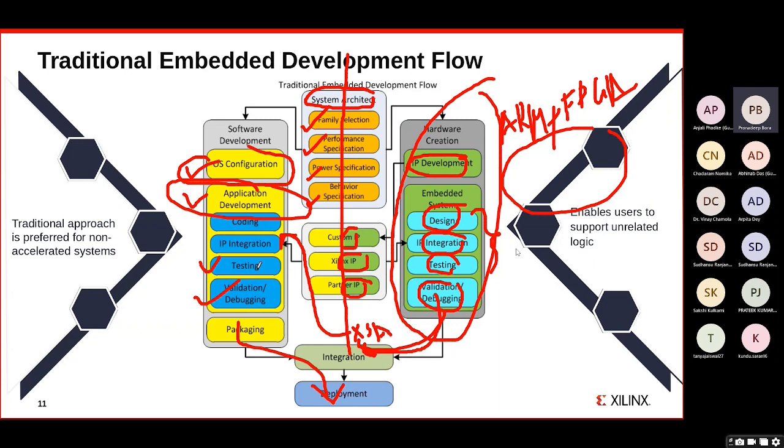Only at the device level, which peripheral to call, what the address of those peripherals is, all those things will be combined, and then the full system will be validated and tested using ILAs, and here we will be debugging the software code, and then we'll be deploying it onto the system. So this is the way embedded system development works.